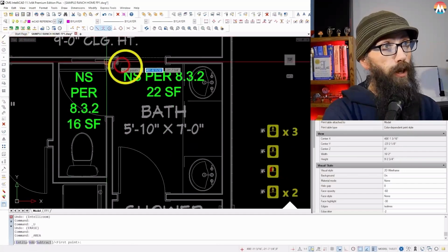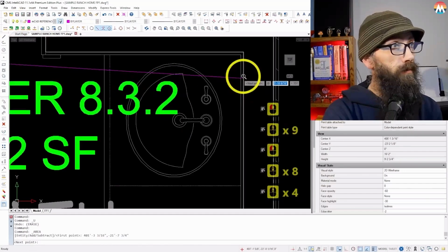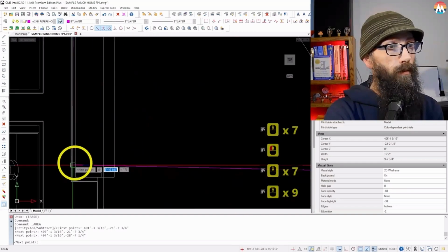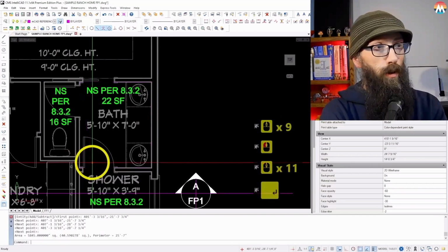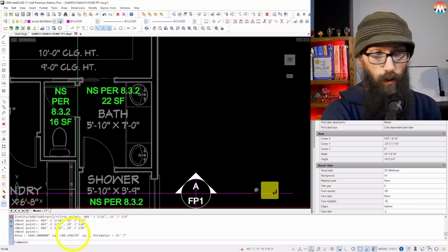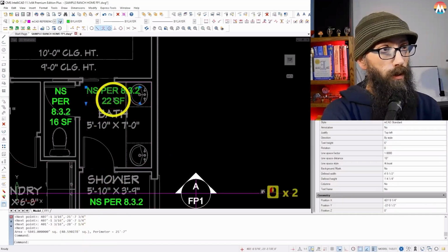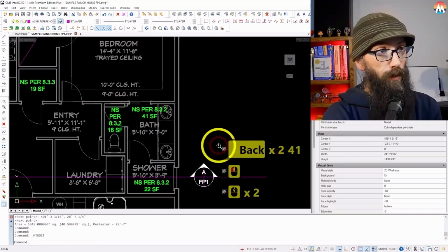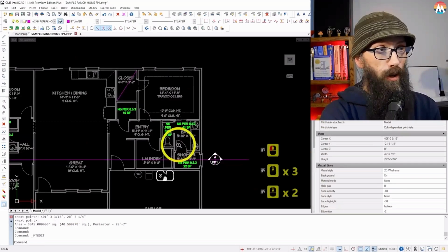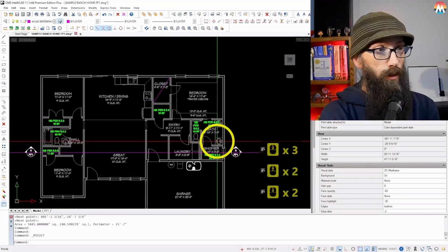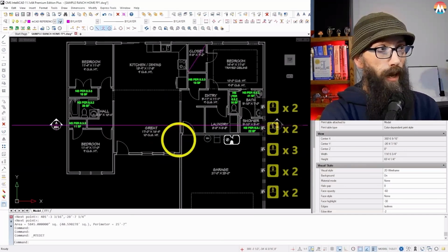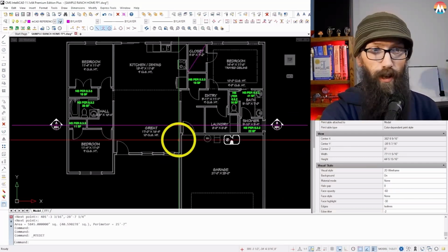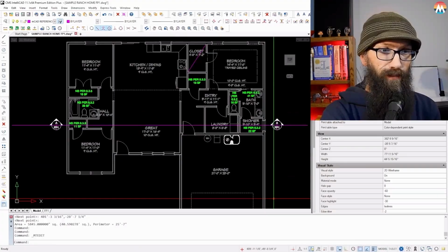Let's go ahead and get this area. All right, that one is 41 square feet. So you can see these numbers, how they would have added up. They definitely would have been over 55. But because they're all individually under that, we don't need a sprinkler. All right, so that is it for our project for areas not requiring sprinklers. We will see you guys in the next video.